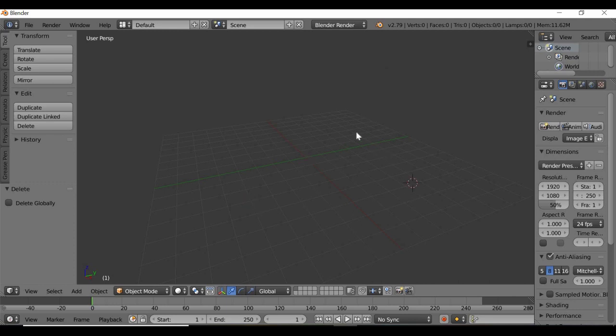Now you see, when you just click anywhere in the viewport, you get a circle. So we will understand why it comes and what that is later on. Right now what you see here is called a viewport, and it says it's a perspective viewport. To learn any 3D program, it is best to use a 3-button mouse, because you will be needing all the 3 buttons to navigate through the scene. So what I'm doing here is scrolling my middle mouse button up and down to zoom in.